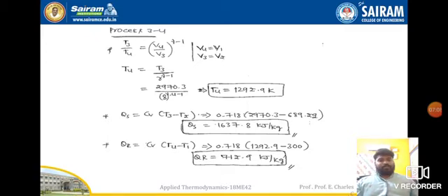To get better clarity, you need to check the PV diagram. You'll clearly understand why V4 is taken as V1 and V3 is taken as V2. So in this equation, you can find out the T4 value, since everything else is known, T3 is already found, right?